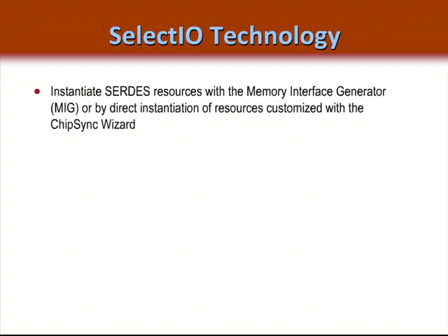The IOBs contain a wealth of technology, as I mentioned in a previous REL, but the newest resource is the SERDES functionality. The SERDES resources offer the ability to encode or decode a signal with dedicated serializer-deserializer logic that is embedded in specific IOBs. This functionality, by its complex nature, offers many options to customize. To make it easier, Xilinx offers two places for designers to customize their SERDES pins.